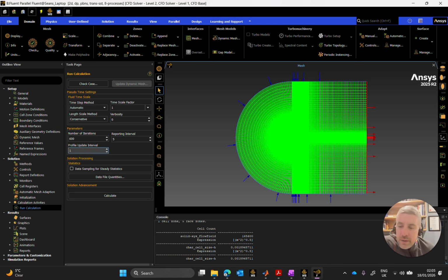All right. Make sure that's up high whenever you're doing a table of design points in a parameter study, because it's not going to tell you has the solution converged out in the table. So you want to give it plenty there to make sure that it has converged. Because you could look at the data on the table, and some of the numbers could be a wee bit off, where you might be expecting, which we'll look at now here in a second, as the angle of attack increases, we should be seeing higher lift forces, and we should also be seeing higher drag forces.